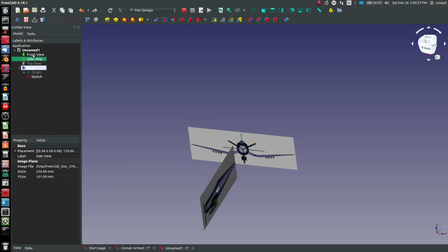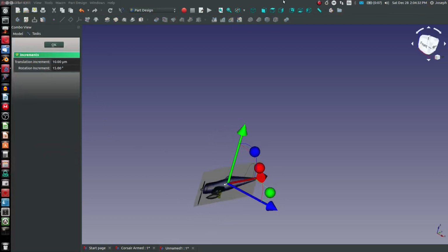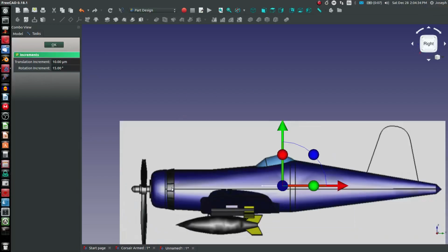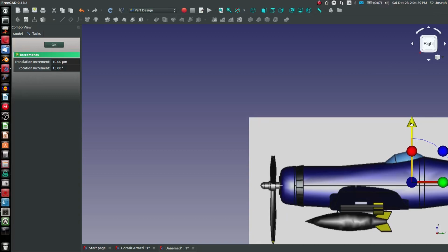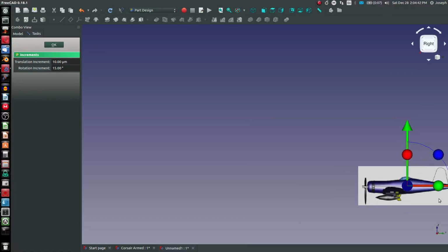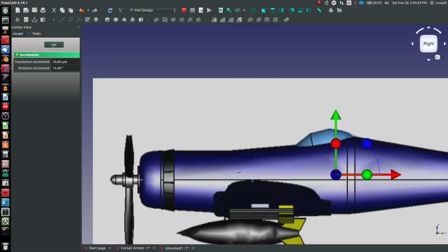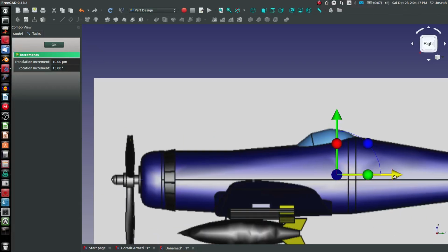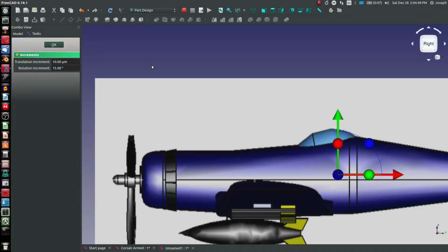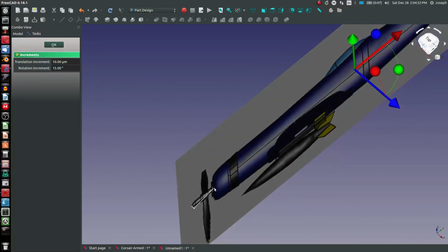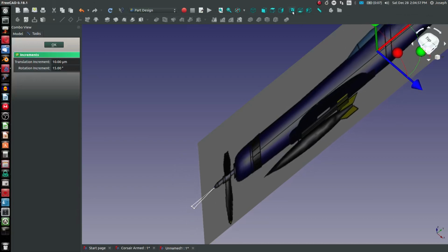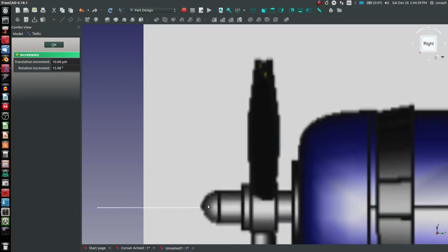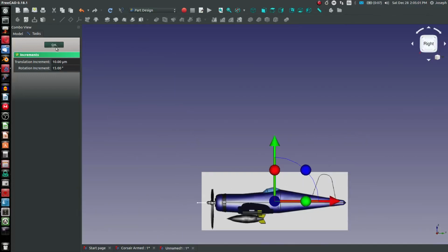Now let me show my side view. And if I double click on my side view and go to my right view over here, I can reposition this side view so that the tip of the propeller is right up front. Okay, so there's my... Oh, and it looks like my origin is right there and not right there, so I'll move this even further back and take another look from my right view. That looks about correct, so we're going to say OK on that.